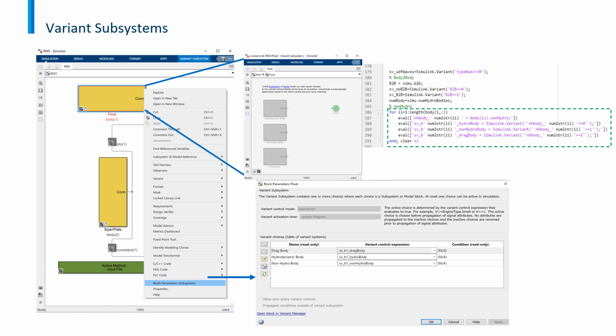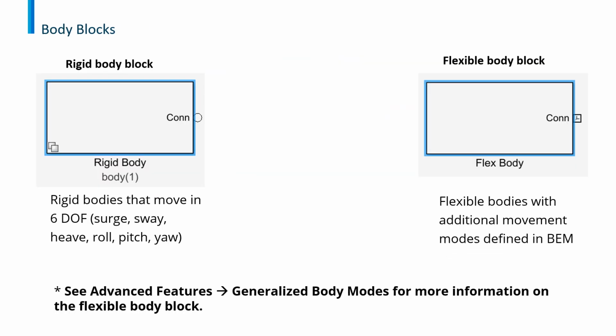Similarly, a drag body is a body whose weight and buoyancy are considered, but hydrodynamics are not considered. For a drag body, however, the drag coefficients can be included in the analysis. Therefore, WEC Sim can incorporate bodies that contribute to the overall system dynamics, but may or may not be subject to hydrodynamic effects.